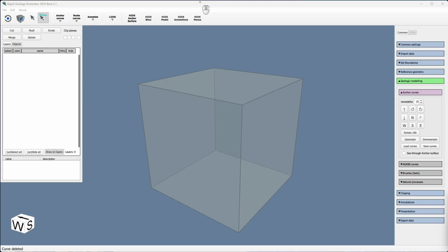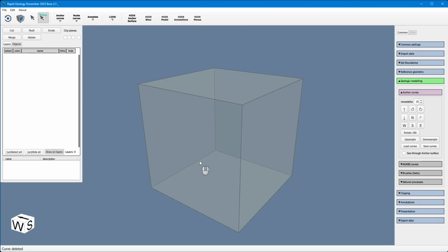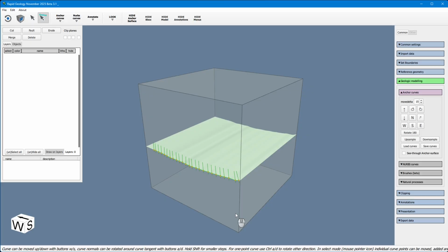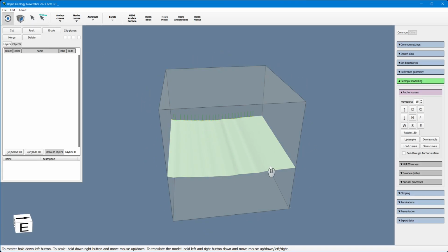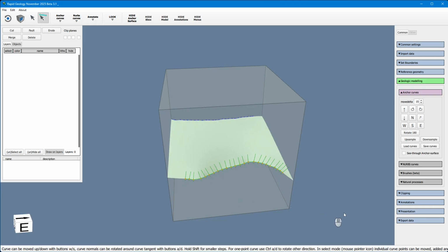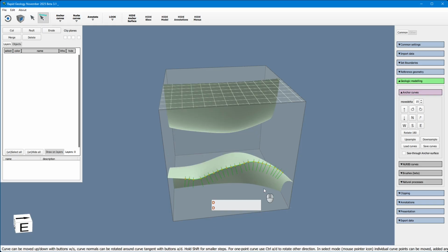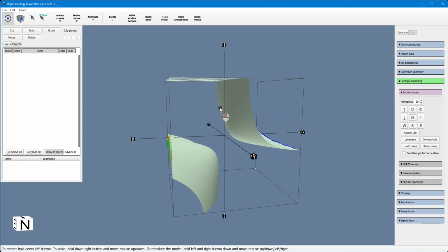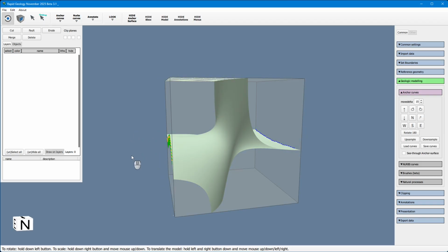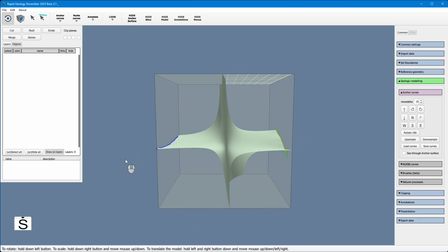When working with these curves and you get a result which doesn't make sense, it could be because one of the curves have sort of flipped normals. So let me demonstrate. Here the normals point up, but if you somehow end up making a curve in a different place, which has the normals pointing down, so let's rotate it so it points down, like this, then you get a very strange surface.